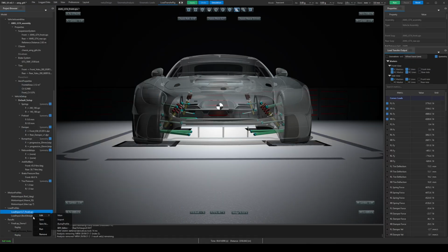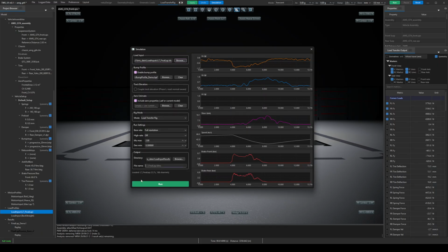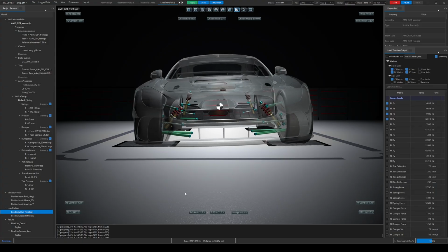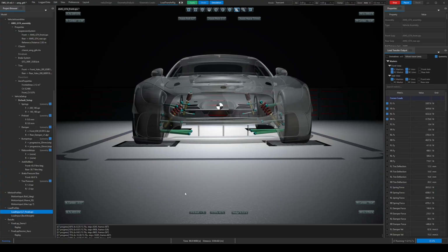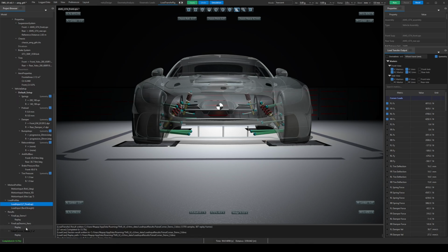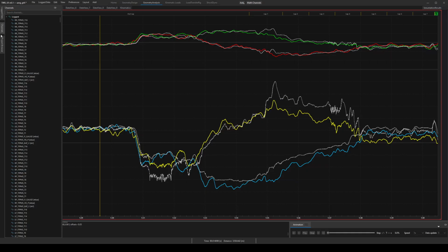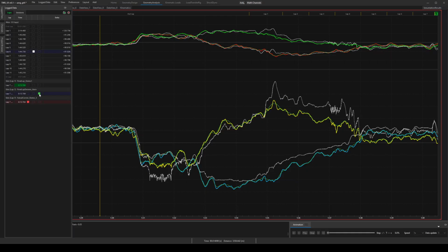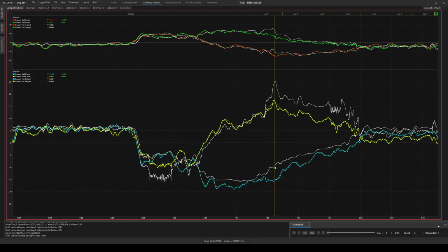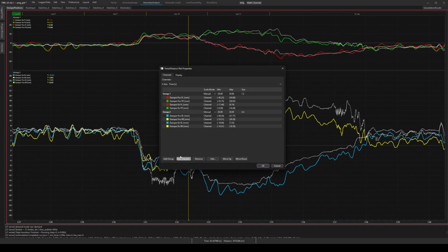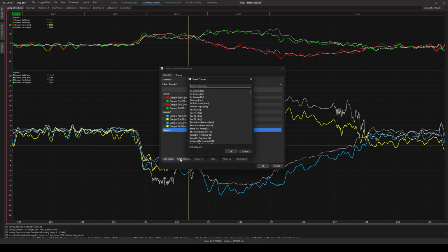The next step is to rerun the same load input, but now with the reconstructed bump profile added to the simulation. Then we compare the simulated and logged results again. Even at this first stage, the reconstructed road surface already captures many of the track-induced features. There is still one area after the corner apex where the overall shape of the damper traces matches, but the compression magnitude at the right rear does not correlate well.